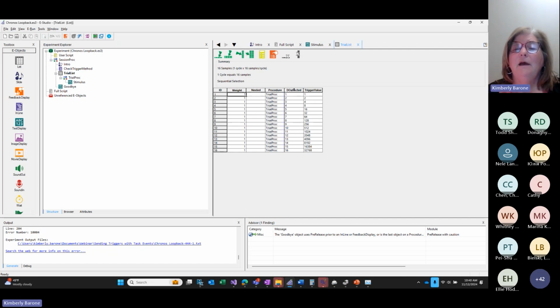What we see here is an independent variable being logged that tells me which digital output we are affecting, which one we are writing to. Now this is one-based, so this is the first digital output, which is digital output 0. This is the 8th digital output, which is digital output 7, and so on. We're only dealing with these last 2 digital outputs here. So we want to affect the 15th and the 16th. And this is the integer value that corresponds to those digital outputs.